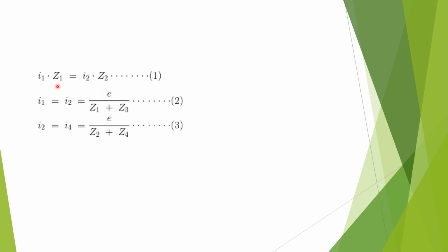So as seen here under balance condition we have I1 equals I3 and I2 equals I4. Now when you equate the real and imaginary parts we get R1 which is equal to R3 by R4 into R2, and L1 which is equal to R3 by R4 into L2. So we get the resistances as well as the inductances.